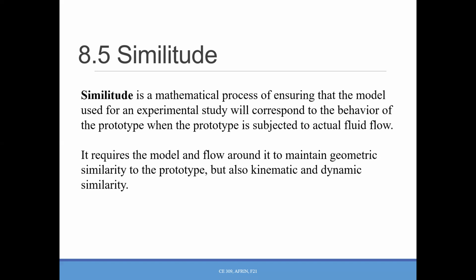Okay, so the similitude is a mathematical process of ensuring that the model used for an experimental study will correspond to the behavior of the prototype when the prototype is subjected to actual fluid flow. Okay, now we need to know what is prototype and what is the model.